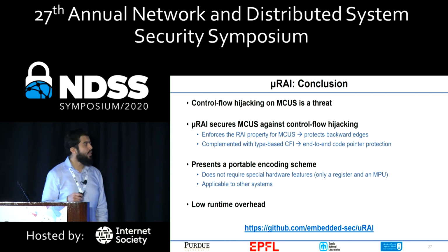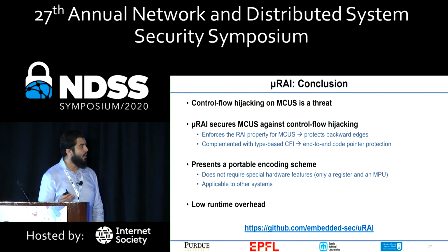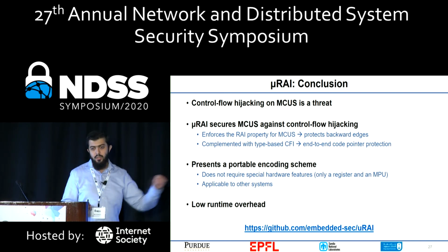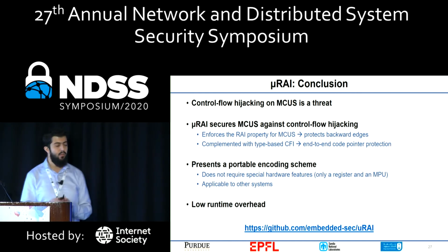µRAI secures MCUs against control flow hijacking. We fully protect the return edge, the return addresses, but also all the evaluation that you saw is complemented with the forward-edge type-based TFI, so we have an end-to-end protection.